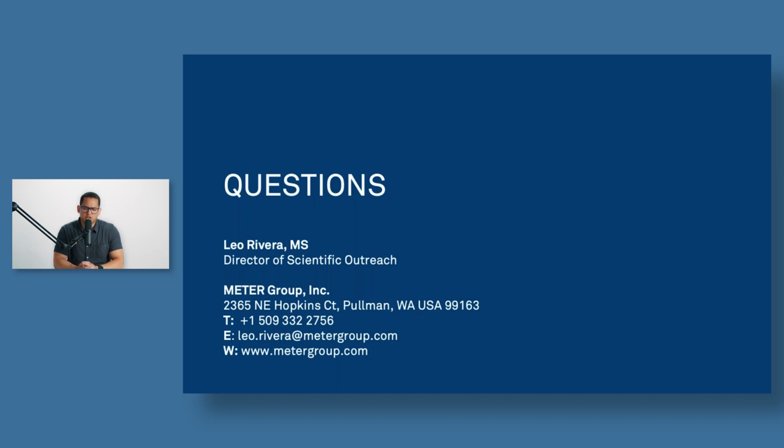You especially see that more so when it comes to the temperature sensitivity on the dry end. But the biggest improvement is the installation approach and being able to install it quickly and easily into the soil. And what's also nice is because of the way they're installed, you don't have to pack the soil around the sensor. Because as you're inserting it into that augered hole, it collects all the soil that it needs around the ceramic to form that good contact. And so we see that it's overall an easier sensor to install.